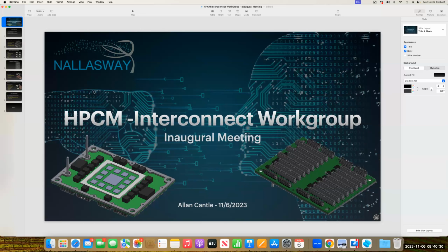So my question is, will those be through BGAs, or is it just using a micro via? Because it will be an HDI board. Everything will be surface mount. The through holes are just around the edge of the board, as you can see. Even the ICs are just SMT.